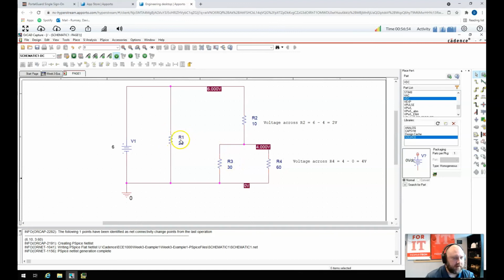One thing you might want to notice here is that the voltage drop across R1 is going to be 6 volts. That's because of a particular configuration that R1 is in. We said that R1 is connected in parallel to the power supply. And when we say parallel, what do we mean? Both the top and the bottom connection of that resistor are the top and bottom connection of your battery.